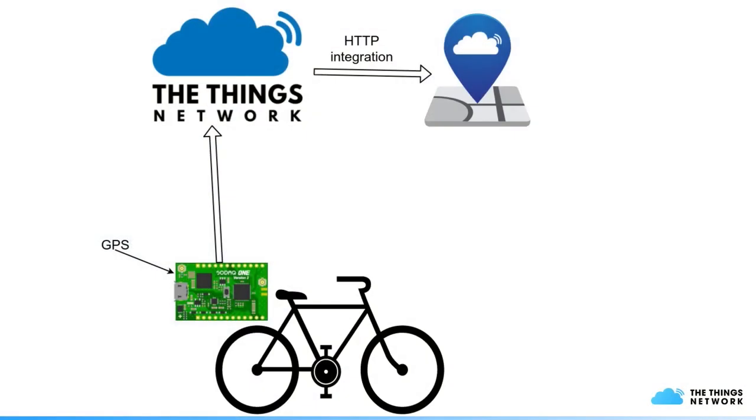A tracker has a GPS receiver on board. It can therefore determine its location by itself. The tracker then sends this location in the payload of the LoRa message. On The Things Stack console, one can send these coordinates along with the metadata of the message directly to TTN Mapper. Let's hook up a GPS shield to our Arduino.